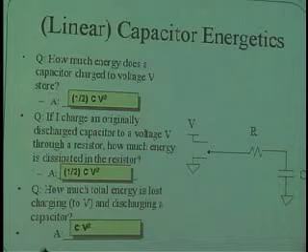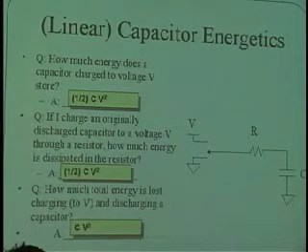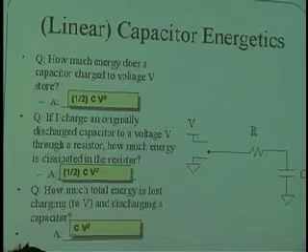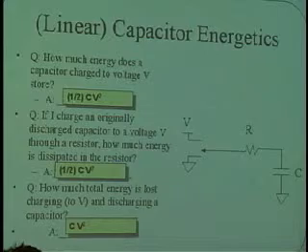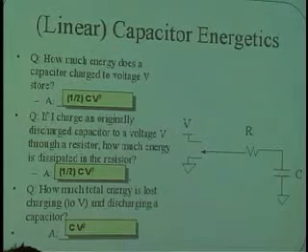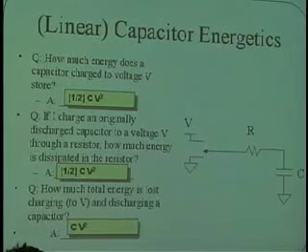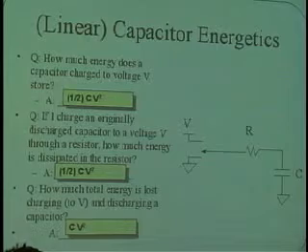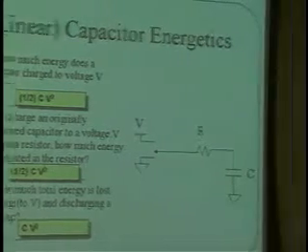It turns out, regardless of how slowly or how fast that process happens, the amount of energy that is stored on the capacitor when it has V volts on it is 1/2 CV squared, where C is a measure of how much capacitance you have. What's interesting is that, again, regardless of how fast you charge it up, how big that resistor is, the exact same amount of energy that goes into the capacitor is also dissipated, is wasted in the resistor on the way.